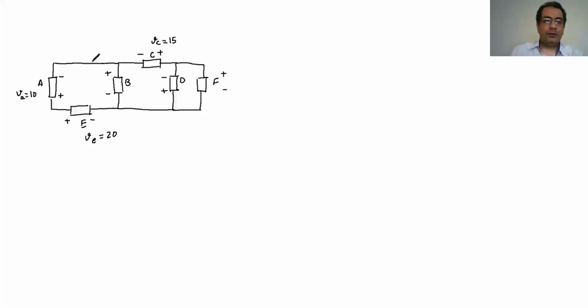So to find the voltage, I would start with Kirchhoff's voltage law. I would consider the very left loop as loop one, and write the KVL in loop one. Sigma V is going to be 0. So if I'm in loop one and I add all the voltages together, it should be 0.